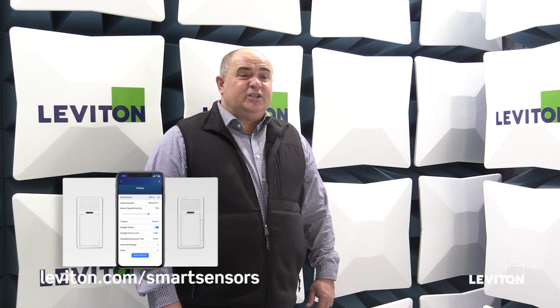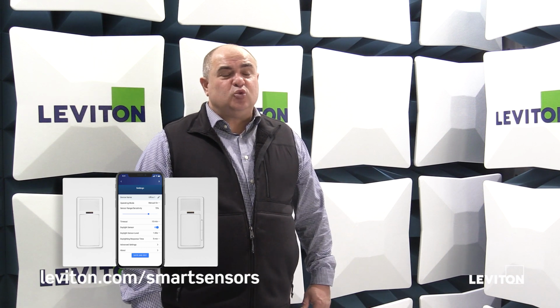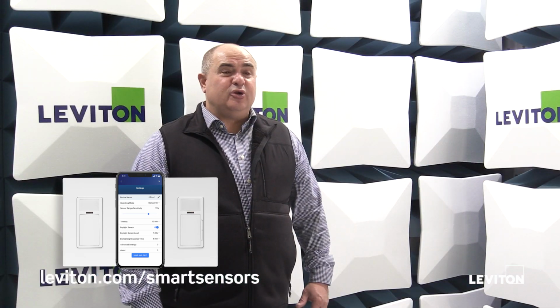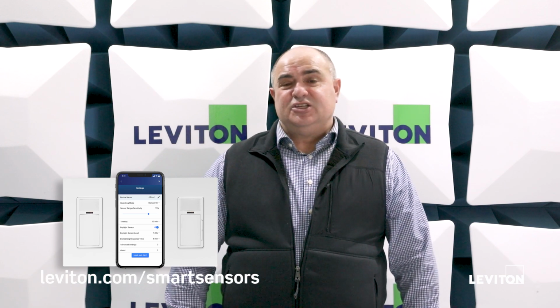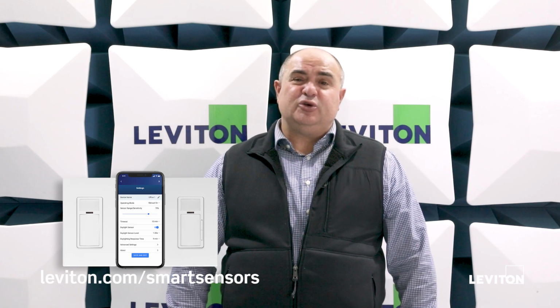And then of course the switching. There still are those areas within a given project where you do want the multi-tech technology, but possibly, for instance, with Title 24, if the space is less than 100 square feet or less than 0.5 watts per square foot, you do not require multi-level control of the fixtures. Switching is a solution. So in those cases, we do have actually a cost-effective solution to have multi-tech technology with